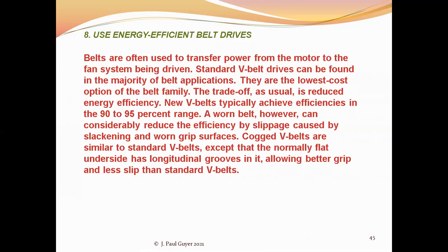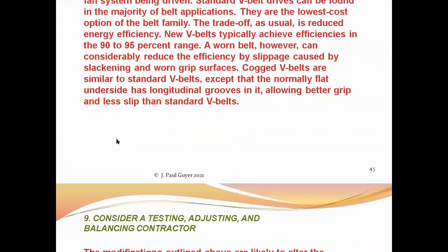And as a maintenance function, inspection of belts is important, because worn belts can slip and result in loss of energy efficiency.